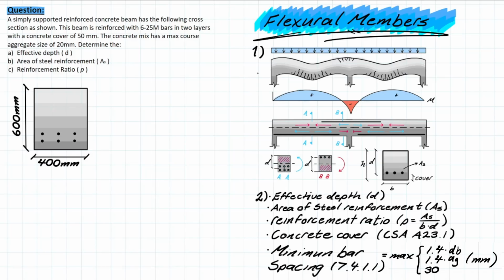But since concrete is cast monolithically, or in other words, poured all at once, we need to consider that there are two different formations. We have simple configurations, and we can also have continuous or indeterminate. So once again, we already covered simple is a two support structure that develops a positive moment, and it's generally supports that are on each end.